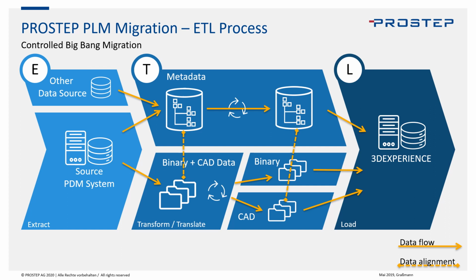And then there's also circumstances where you can get corrupt data. That is especially evident with CAD data. Generally, CAD data with the PLM, when it's opened up, does some introspection, and then you can resolve other dependencies that are only really known in the file and not within the PLM database itself, so that all the dependencies can be loaded, and you dynamically load those dependencies and save them out. Without that, you might miss files that are associated with it. You might also miss renaming of the data, things like that. So you have to be careful about the APIs that you're using on export.